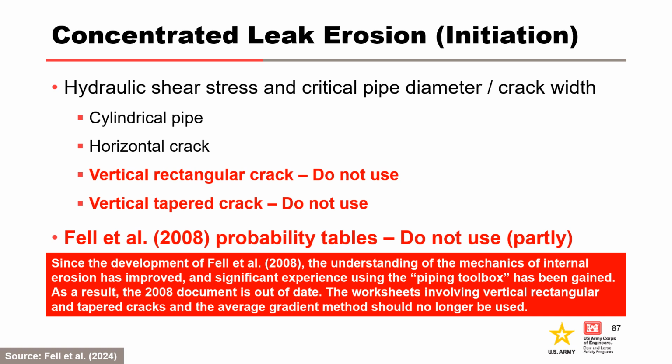Since the development of Fell et al. 2008, the understanding of the mechanics of internal erosion has improved, and significant experience using the piping toolbox has been gained. As a result, the 2008 document is out of date. The worksheets involving vertical, rectangular, and tapered cracks and the average gradient method should no longer be used. An update to the RMC Concentrated Leak Erosion Initiation Toolbox is being developed for open vertical, rectangular, and triangular cracks.